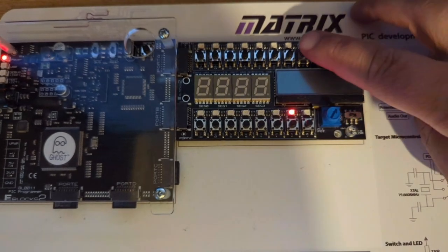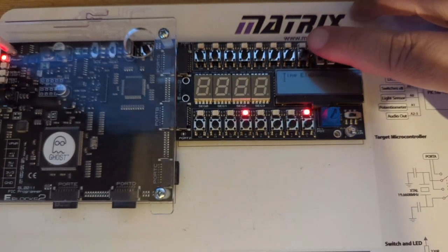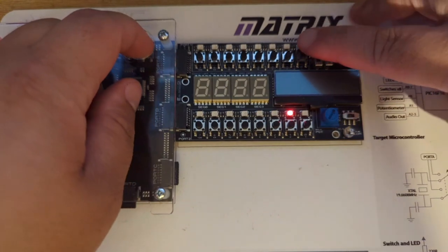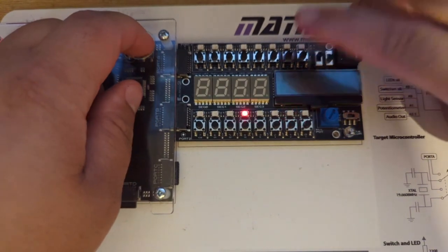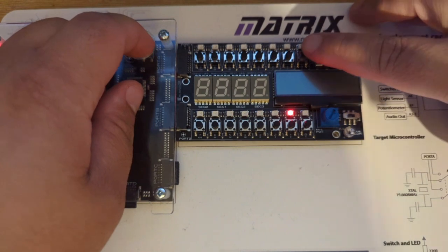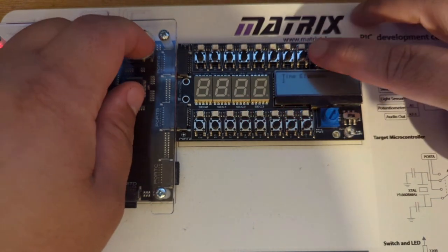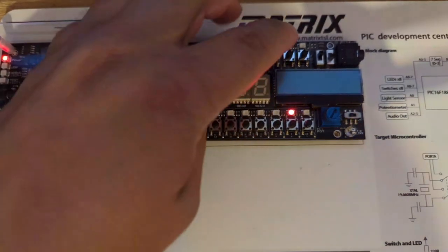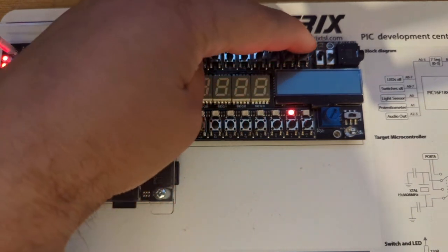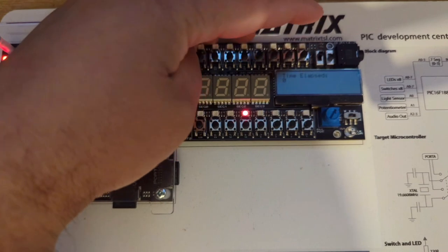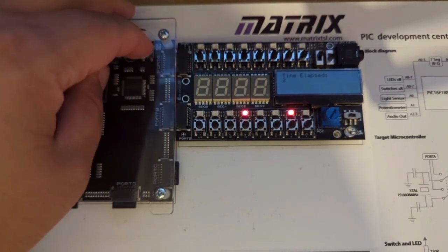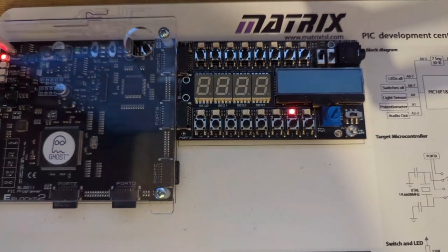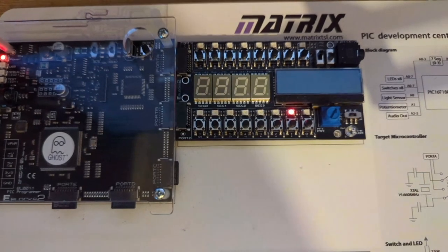So if I press A0 now, immediately it should start. Ooh, it started and it didn't miss a tick. It just went. Alright, ready? Oh, look at that. And if I just tap the button, like just rapid. Oh, ready? It catches it every time because that button press, even though I'm pressing it fast, is probably still 250 milliseconds or something like that. So that's hundreds of cycles for the microcontroller. So it sees it. Oh, we've done an interrupt.